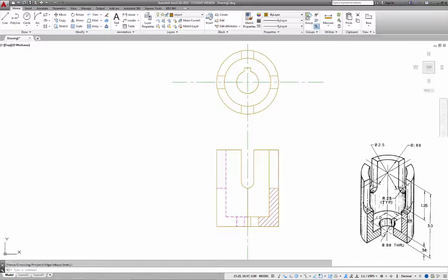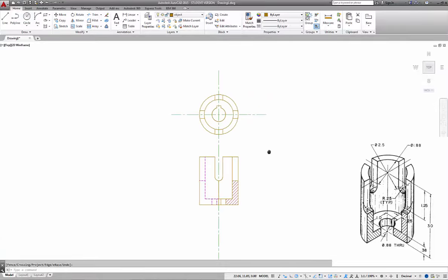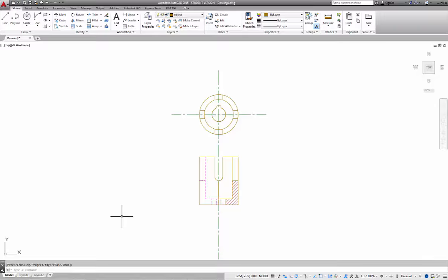view. So now we've taken this isometric section with the sketchy drawing and the somewhat difficult to see dimensions and created an orthographic section view. The next step would be to put dimensions on it, put it on a layout with a template, print it out, and turn it in.